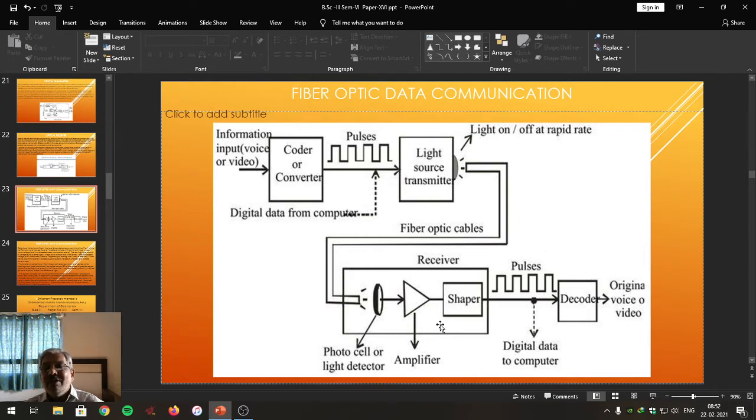Thus, after comparison, incoming varying electrical signals are going to be converted into the digital pulses. These digital pulses are provided to the decision making place where the proper decision is taken regarding incoming signal, and it is coded into either 1 or 0 depending upon the comparison between incoming signal and the threshold voltage level defined.